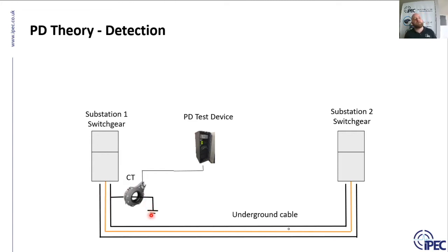Now, when it comes to the lower end of the medium voltage, maybe 11 kV, 10 kV, whatever the standard is in your country, sometimes this may not be the case. Either an installation engineer has made a mistake, or it's not a standard policy to isolate the earth from the switchgear. When we get to the higher voltages, the HV level and the EHV level, in the hundreds of kVs, obviously the earth is definitely isolated from the switchgear. But in the lower voltage levels, this may not always be the case, and it's always worth checking that situation out before looking to apply this type of technology.